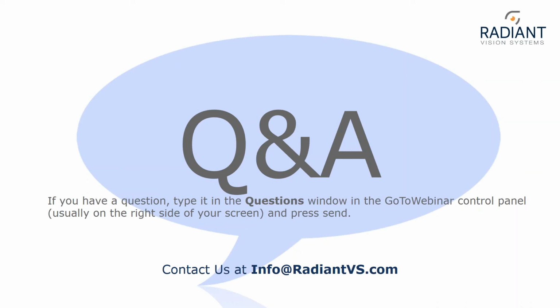There's a question here regarding, does this method work for correcting color uniformity? As we are correcting, our goal is to drive the red, green, and blue pixels to have the same response. Inherently, we could correct for a color non-uniformity caused by pixel level variation. If we measure the native colors of the red, green, and blue pixels, we can make sure that the overall color of the display is driven to a specific white point.